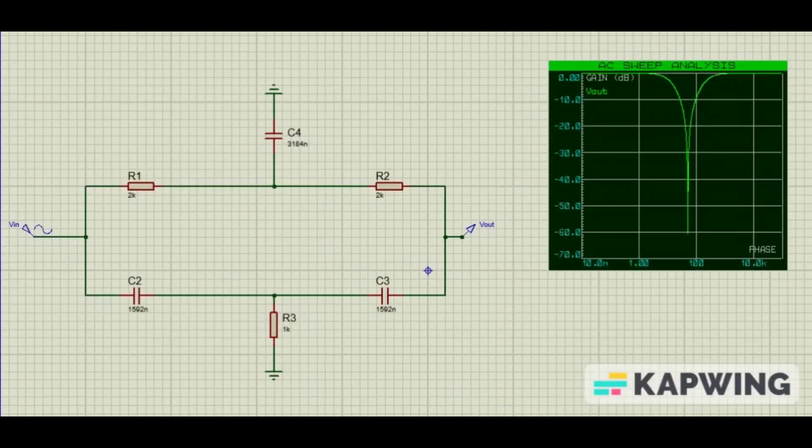In the next step, we go to designing the notch filter. A notch filter is a type of filter that removes a specific frequency known as the center frequency. So after removing all frequencies outside the ECG signal range, we need to remove any noise that is present within that range. One of the most common types of noise in ECG signal is power line noise, which has a frequency of approximately 50 Hz up to 60 Hz. In our country, it is 50 Hz. So we will eliminate the 50 Hz frequency.